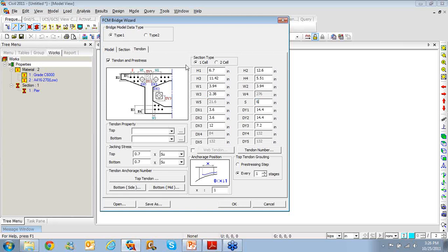This particular step requires a little bit of thinking and work to break down the entire profile that you have from some DXF format or some other Excel input. But once that is done, it will certainly be very helpful for generating the model using the wizard that includes all the construction stage analysis.